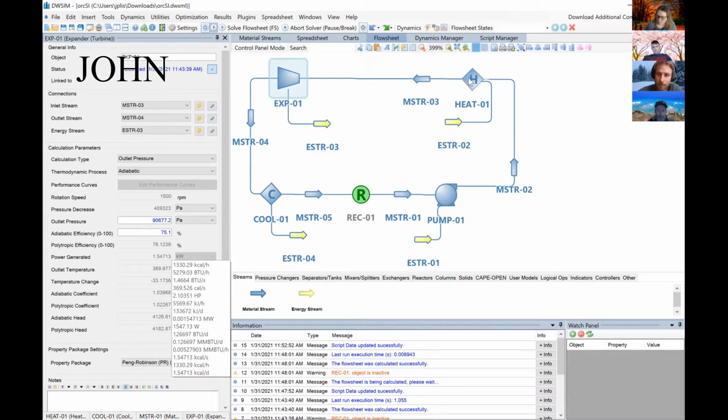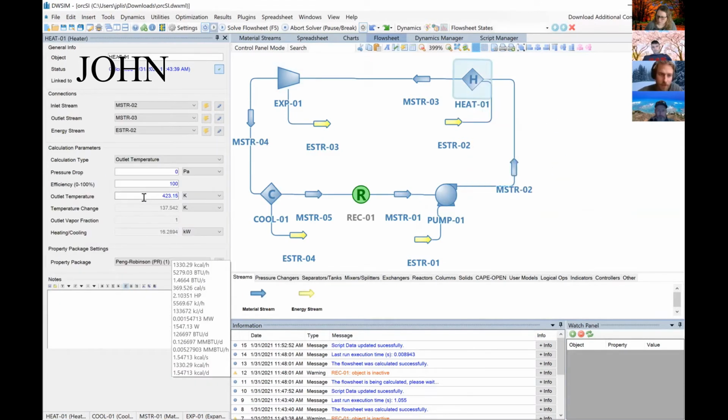And then we can also determine how much energy we need to put in via the heater, be it through the asphalt or the solar evacuated tubes. So right now we're sitting around 16. Our best guess is we're going to need to put in 15 to 20 kilowatts of heat energy in order to get our desired 1 kilowatt out of the turbine, at least with the current expected mass flow rate.